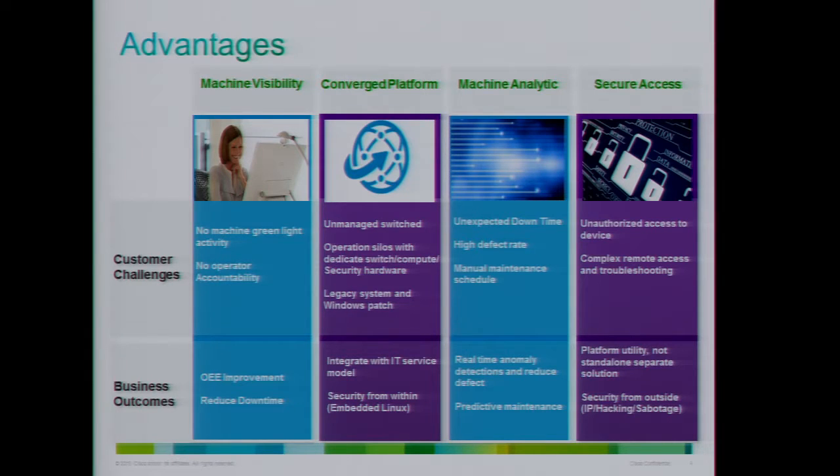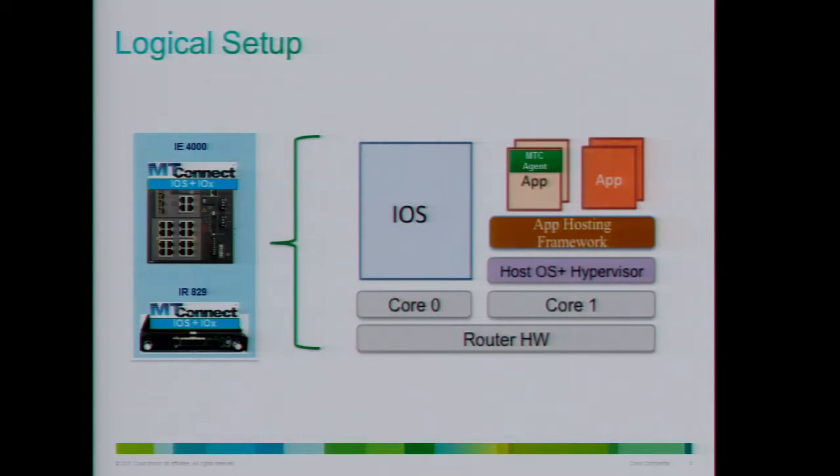You can also do NAT. NAT is called Network Address Translation. By doing that, you're basically taking your machine into a subnet where your OE doesn't have visibility to it. And you can do one-way NAT, two-way NAT, however you want. So it's a very good example of how you can secure your plant floor from the internet.